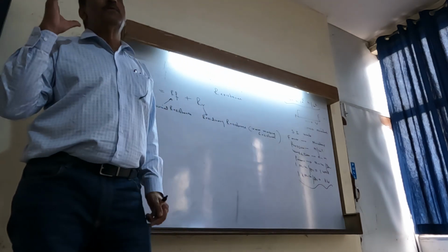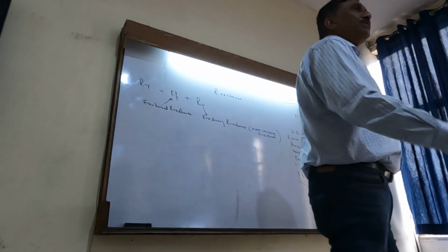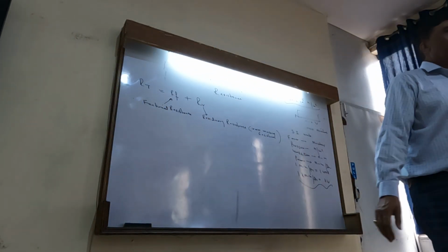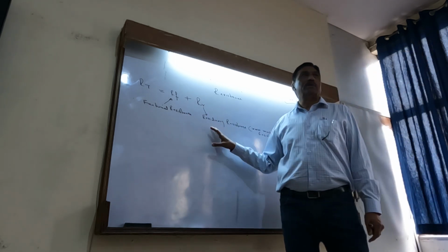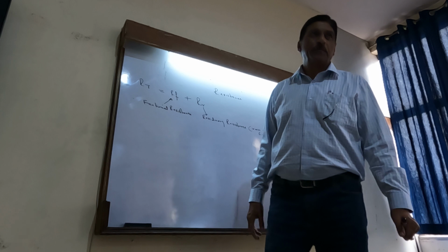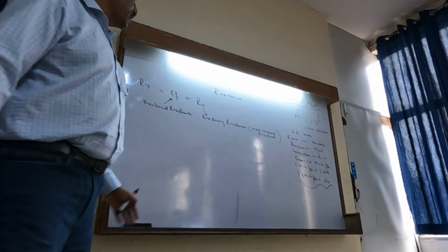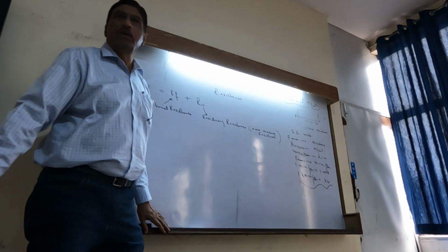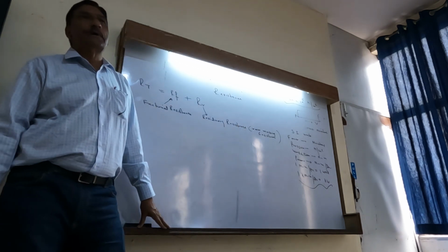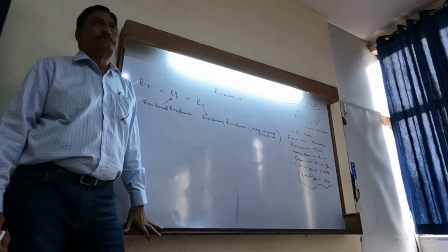So in order to create these waves, the energy has to come from the ship's propulsion only, and therefore it is also part of resistance. The sum of these two is called the total resistance of the vessel. Residuary resistance, RR, is the symbol for writing these two.